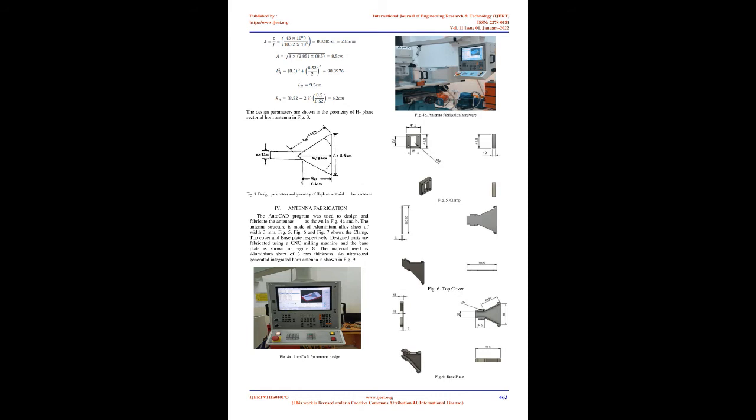The pyramidal horn shown in Fig. 1c is used as a primary gain standard since its gain may be calculated to within 0.1 dB by knowing its dimensions. By varying the rectangular aperture dimensions it is possible to control independently the beam widths in the two principal planes, E-plane and H-plane. Circular geometries are also in widespread use, and shapes such as elliptical and superelliptical provide variation required for beam shaping. A special case is the sectoral horn, which is flared in only one plane and thus radiates a broad beam in the plane orthogonal to the flare.